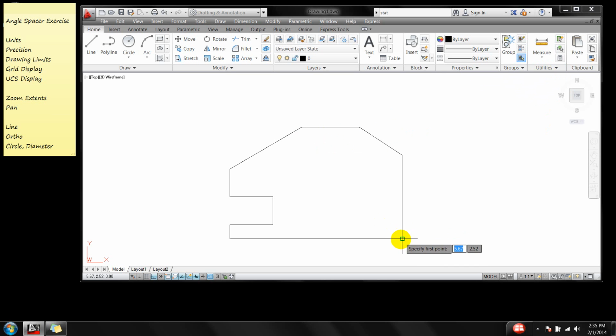So I need this to be 1.5. If I left click on that, then it tells me my distance here, 1.5. Alright, I can left click on accent, right click again, measure geometry, select distance, and I can actually, I don't even really have to click anything. As soon as I snap to it, it's telling me that I've got 3 inches here.